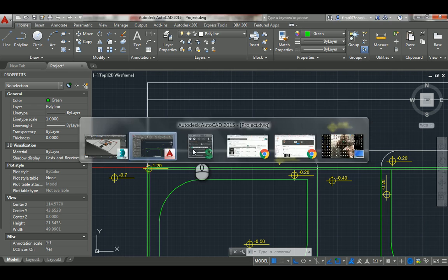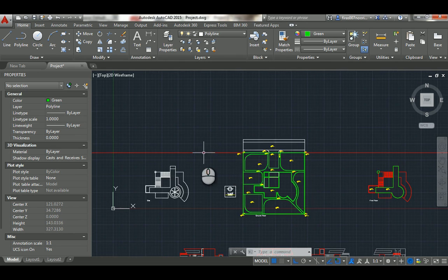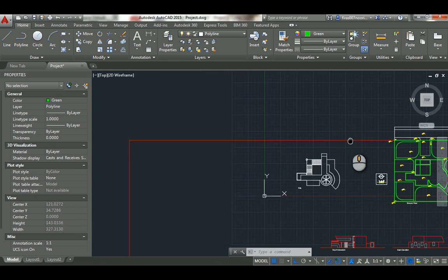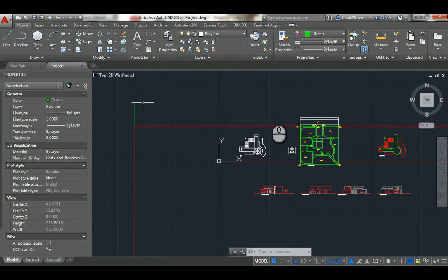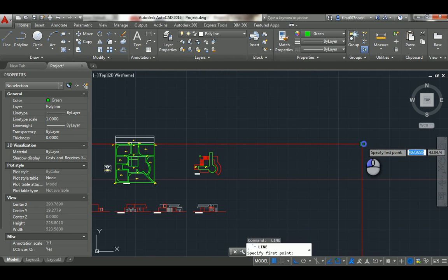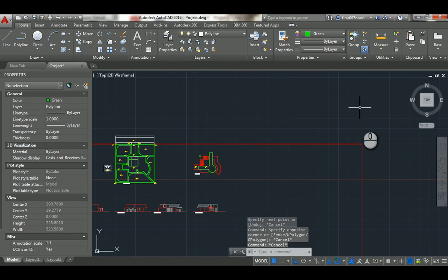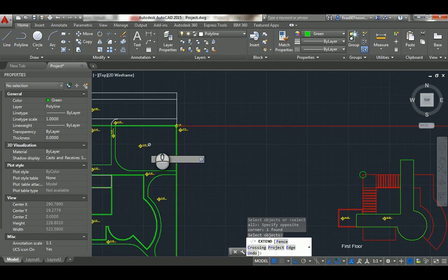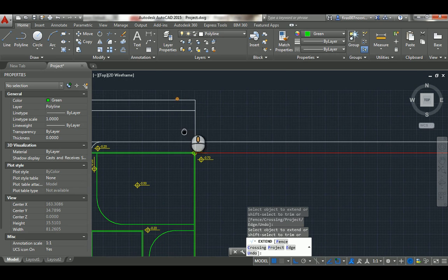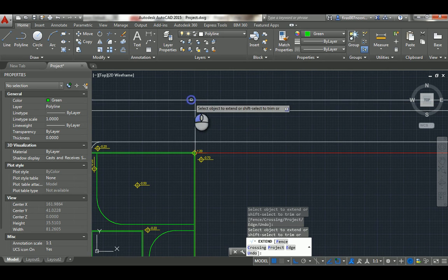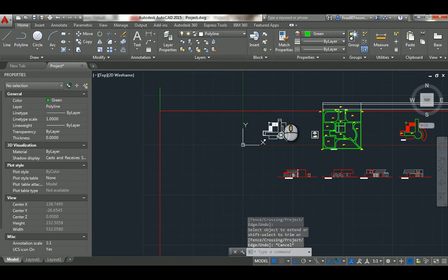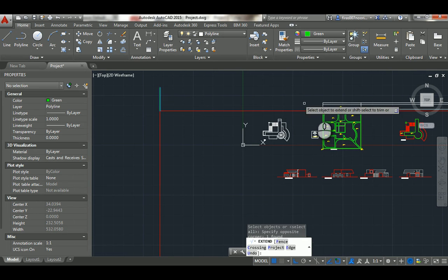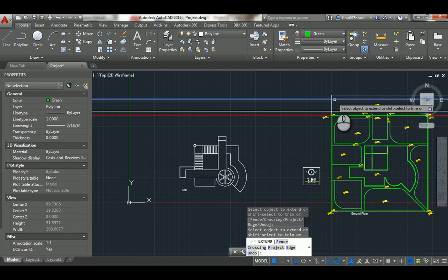So I'm gonna go here and try to model the curb, the same technique, except that I'm gonna draw one line here, up, and another line here, and I'm gonna select that line and then extrude all those to it, and the same thing here, select this one and make all those lines go to it.